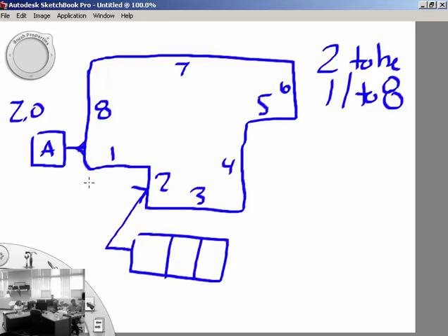Okay. So then, obviously, since that's there, we need to let the feature control frame reflect that we're going to be referencing that one. Okay, so what goes in the middle box here? 2.0. I'll just do 2 because it's small. And what goes right here? The parallelism symbol. So how about that? Good so far? Yep. All right.